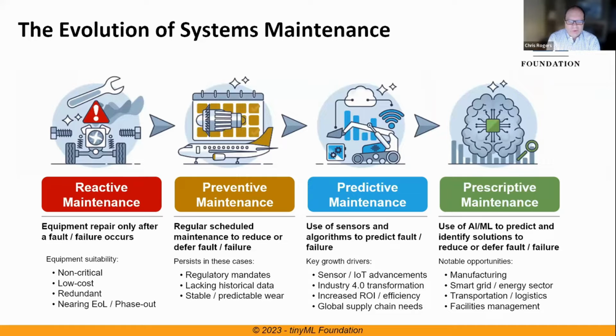So there's no great insight or intelligence into this other than some upfront analysis on mean time between failure that drives recommendation and general manufacturer prescriptions about a periodic maintenance schedule. So there's no closed loop process here. It is just a calendar-based or usage-based approach to providing regular maintenance.